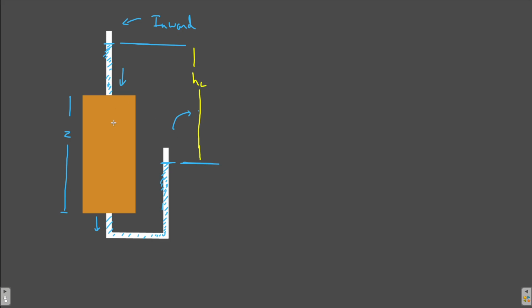Since the water is in motion, it is flowing, it is dragging the soil mass, and it is getting a head loss. So there will be a seepage pressure experienced by the soil, and that seepage pressure PS is equal to the total head loss into gamma W.